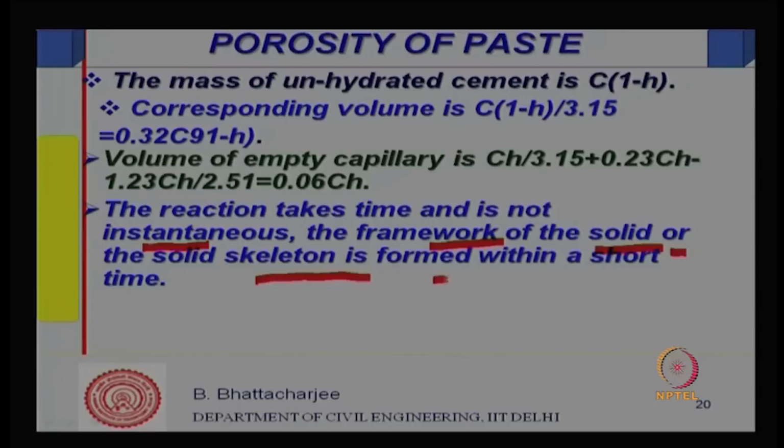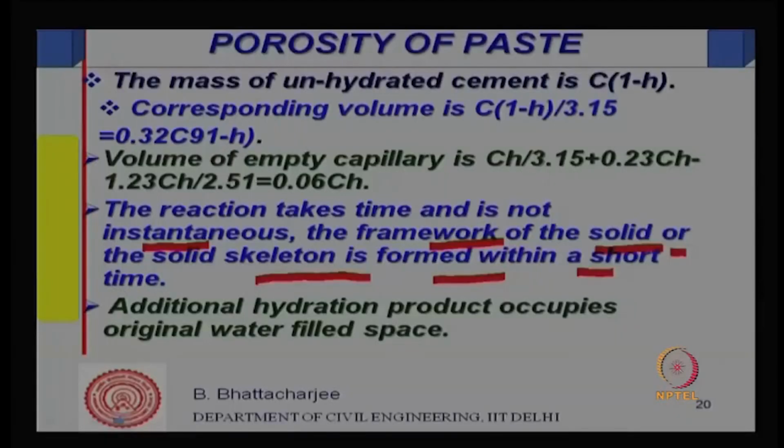So the solid skeleton is formed within a short time, and the rest of the hydration product occupies only the space available within that skeleton. Additional hydration product occupies the original water-filled space within the skeleton.